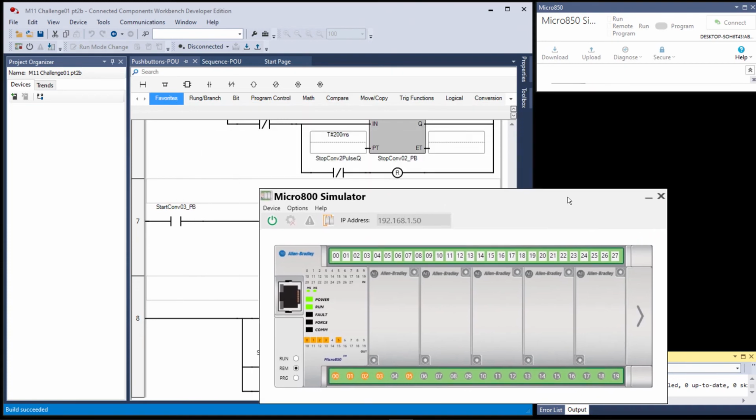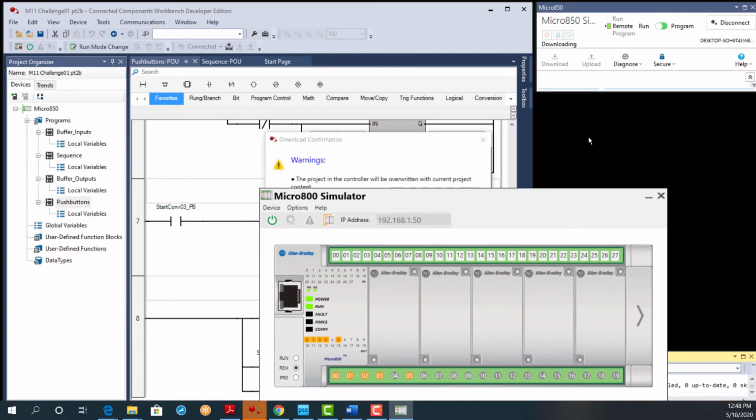We'll find out. By the way, if you're having trouble with Watchdog timer faults, in the manual we gave you a couple of options. One that's popped up more recently is, instead of going to Task Manager and going to the simulator and knocking the number of CPUs down to 2 or 3, do that for CCW in general, and that seems to work better. Now, by the time you watch this lecture, it may no longer be an issue.